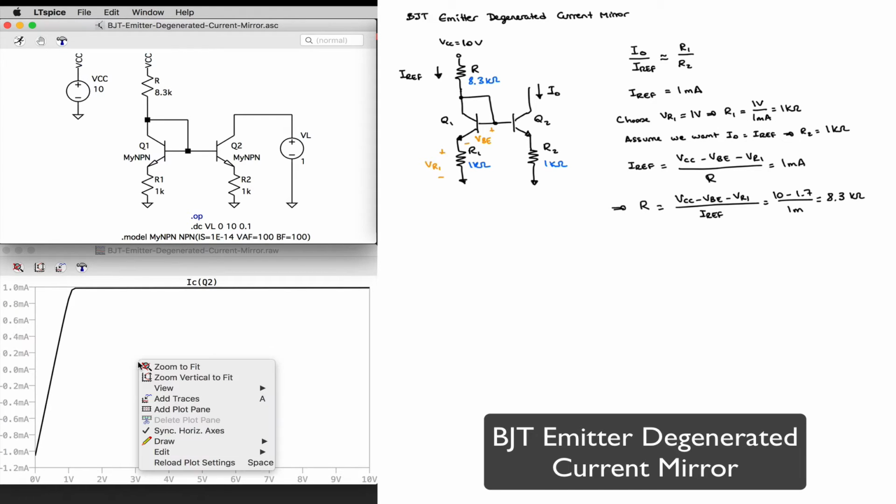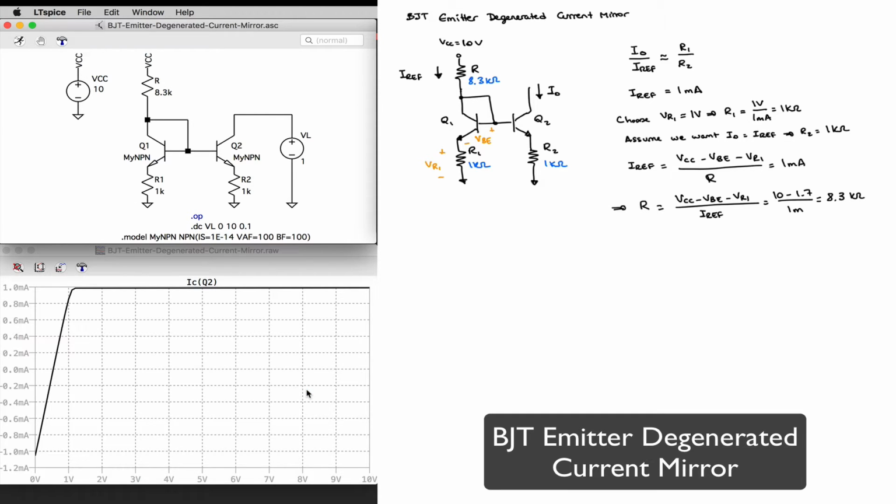I can still go ahead and measure my output resistance. And it's really difficult to see really a slope here, but if we use the cursors, we're going to see how the output resistance is not exactly equal to 0. Of course, we haven't done the calculations on this, so let me go ahead and do those. But we are expecting, in this case, the output resistance is going to be equal to, I'm going to write my assumptions as I did before.